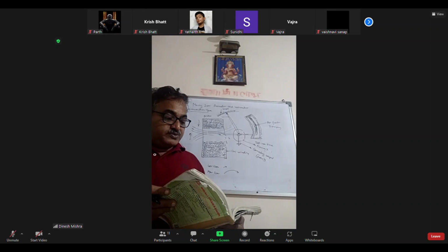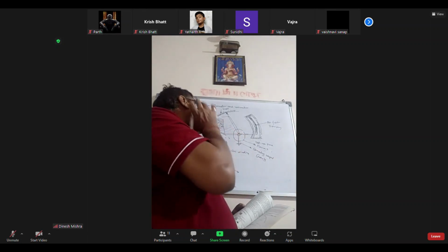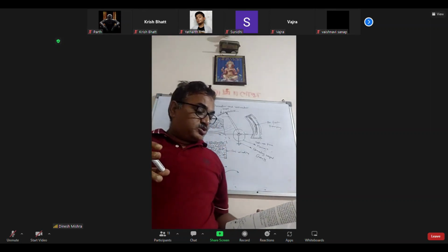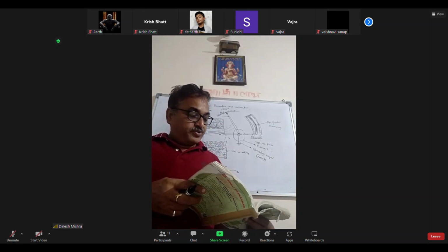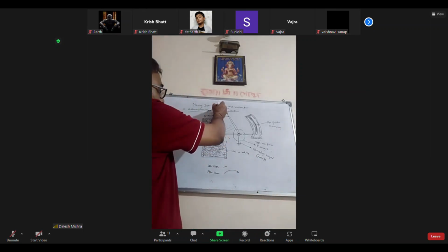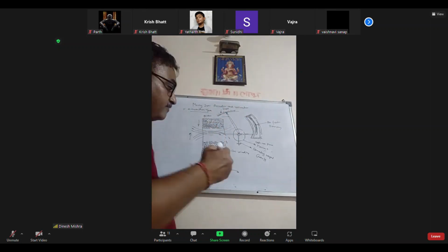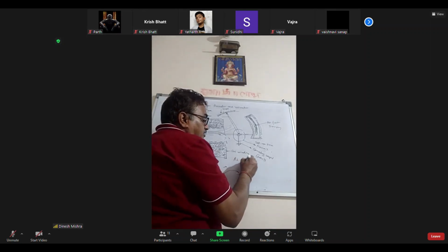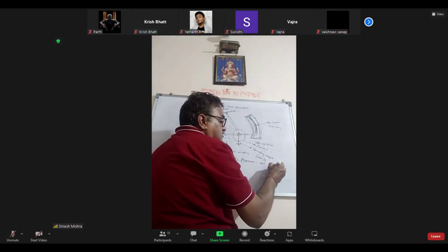The arrangement of this friction damping, which one is it? इसमें कौन सा controlling है? Gravity control is there. And friction कौन सा है? Air friction damping is there. So if the instrument is to be used as an ammeter, the coil has comparatively few turns. This is very important. The same instrument can be used as an ammeter and a voltmeter. When it is used as an ammeter, the coil has a lesser number of turns.